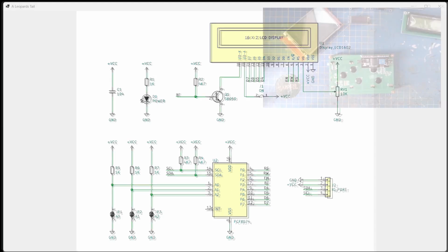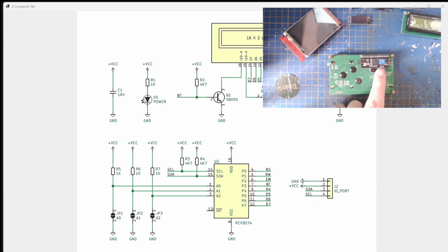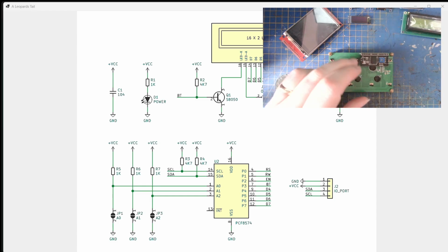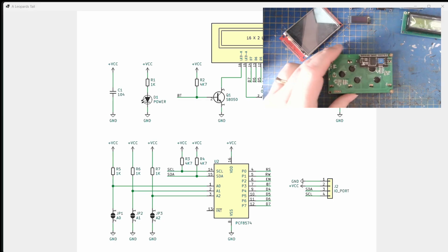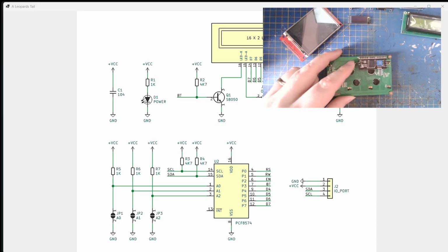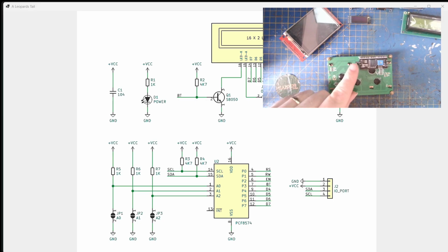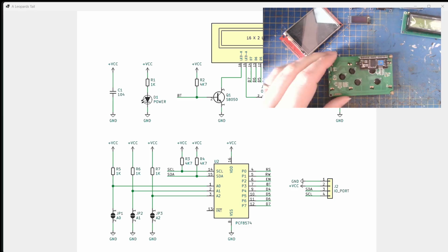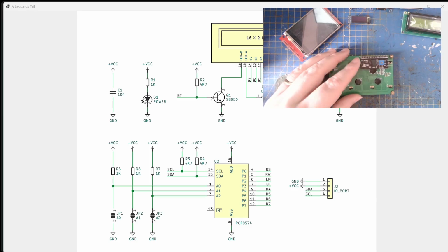We have also got these little pads down here. Now these are these things over here. This has some more pull-up resistors. This sets the address this thing will respond to. We're not going to change that, and if you've only got one of them, you don't need to. This little jumper here is, do you want to use a different power supply for the backlight? Which we don't, so we just put that connector on there.